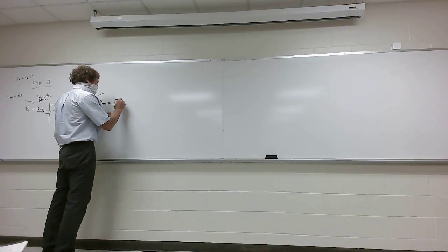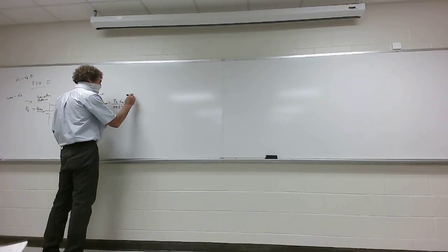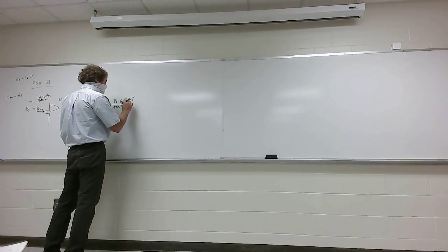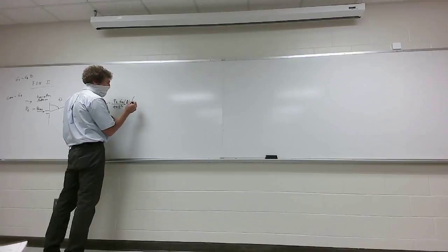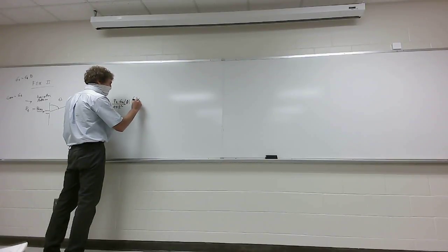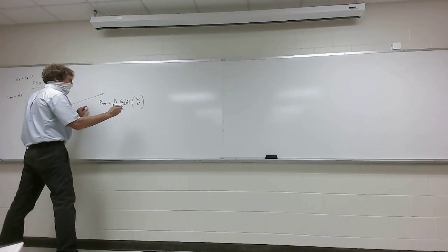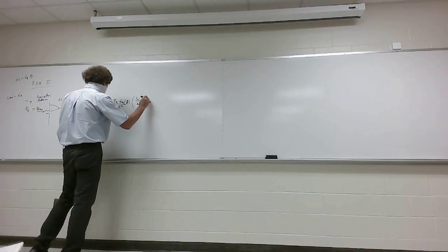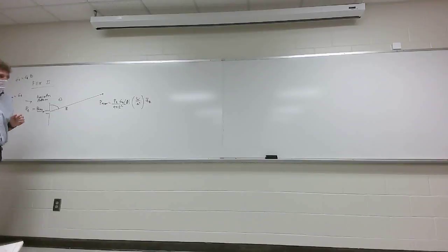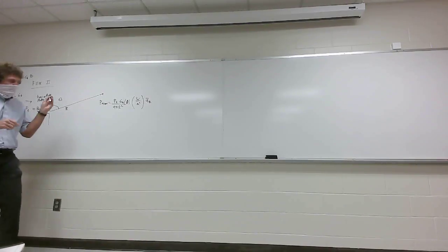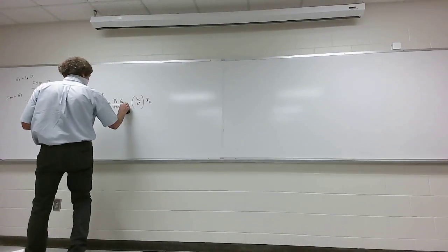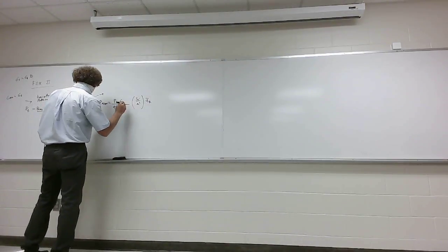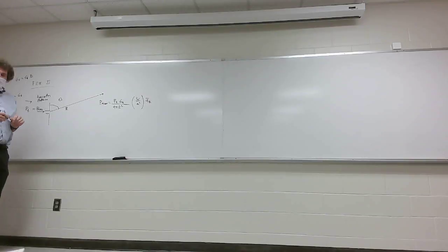So this will be a function of angle, that's the power density. Well, it'll actually be a function of angular position. Could be a function of phi as well. This is the power density in watts per meter squared. And technically it's in the R direction if you assume that this antenna is at the origin. I'm trying to keep this simple. Actually, let me get rid of that theta because it might confuse some people. This is just the gain in the direction that's associated with this point.